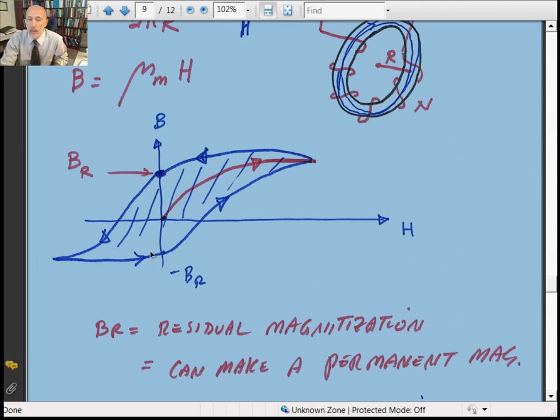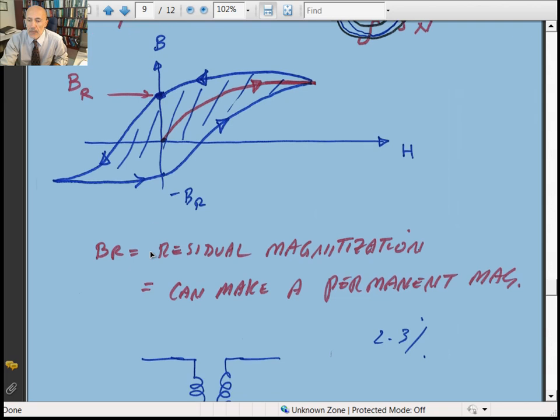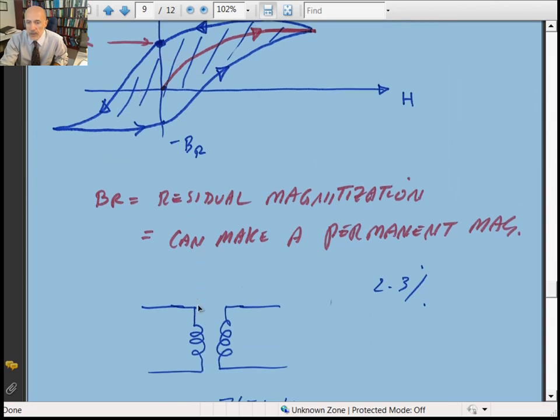Now, power companies, one way to reduce this, the manufacturers of the ferromagnetic materials, when they build the transformers, they add some impurity of silicon, anywhere from 2 to 3% impurity, such that it minimizes this area.